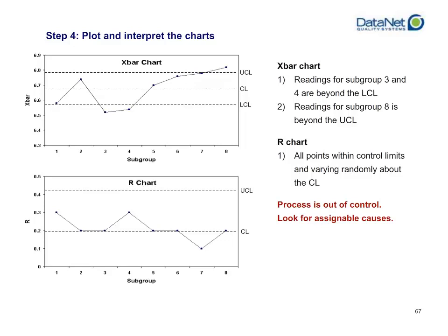Now, it doesn't necessarily mean that you've fallen out of specification, but the process itself has fallen out of control of what historically the data was expected to do. Afterwards, it looks like your process started going back in control again, but once you hit your last subgroup that you plotted, subgroup number 8, you were out of control, violating your upper control limit.